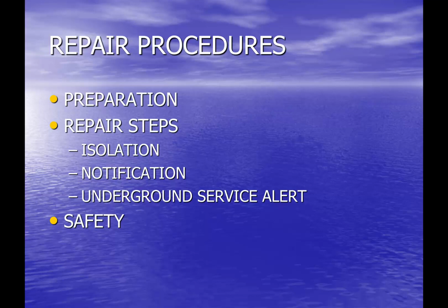We also have to be concerned about the public, and that means looking at making sure that either pedestrians are handled, traffic control is managed, making sure that all of our staff are using the proper personal protective equipment, especially hard hats, eye protection. We can't use an emergency as an excuse not to properly shore a trench. Anything 5 feet or deeper, we'll talk about that when we get into excavation as well, but anything 5 feet or deeper has to be shored. It is just purely a safety issue.